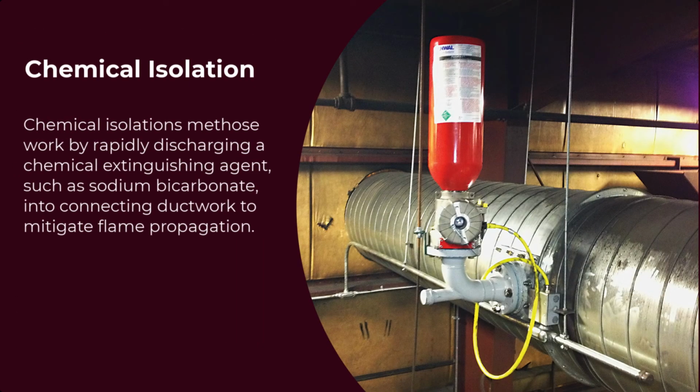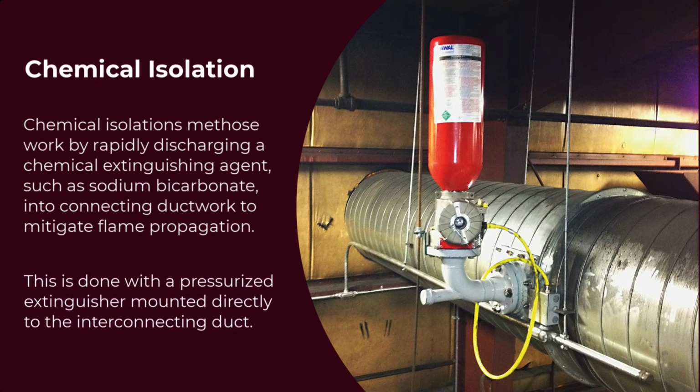Chemical isolation. These devices work by rapidly discharging a chemical extinguishing agent such as sodium bicarbonate into connecting ductwork to mitigate flame propagation. This is accomplished through a pressurized extinguisher mounted directly to the interconnecting duct.